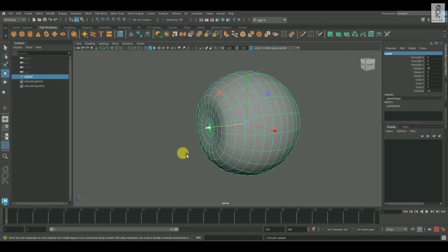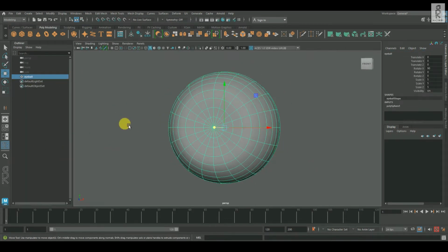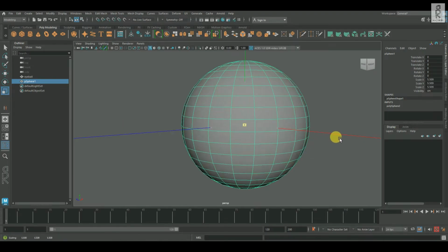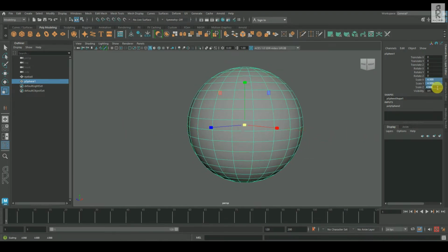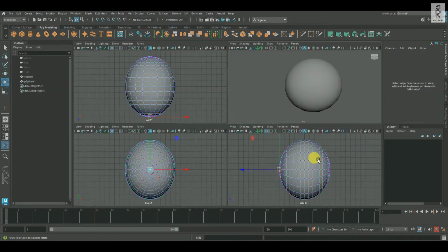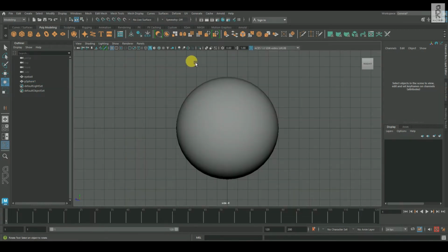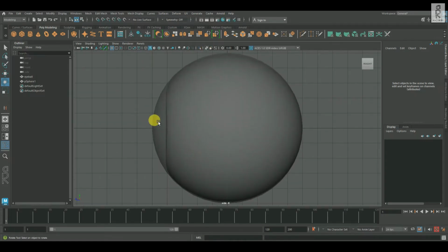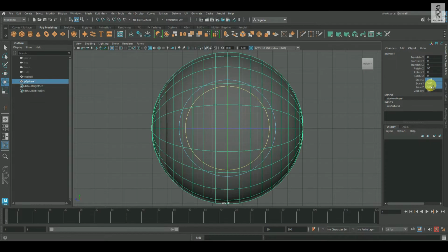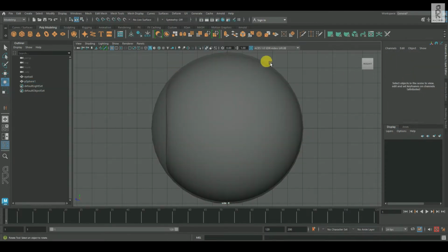Now let's create the sclera, which is the outer transparent portion of the eye. Take a sphere and increase the scale to 5. And then rotate it to 90 degrees on the x-axis. Then go to side view, and then I will turn on the X-ray mode, so that we can see through the mesh. I will increase the scale of the sclera to 0.05 so that there will be a little gap between the two.